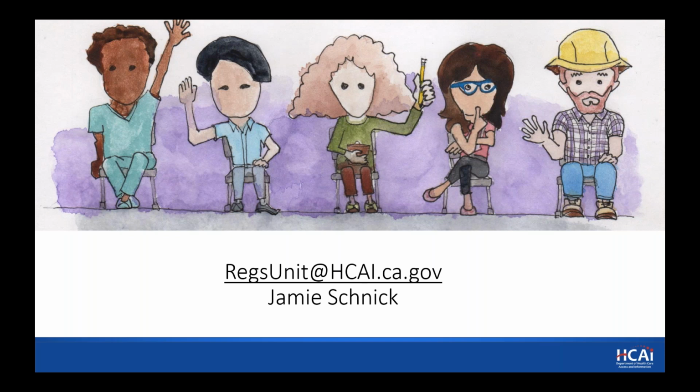Thank you. Next question, can a transformer be installed above the panel it serves within the dedicated panel space? Would it violate the code section 110.26.3? Yeah, that would be a code violation. Short and sweet. Thank you, Jamie. Next question.